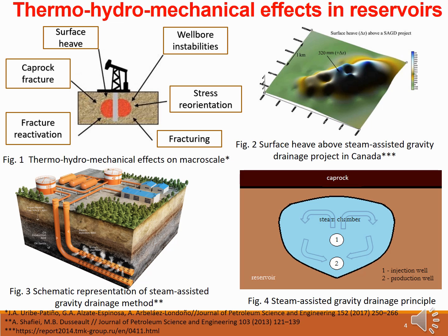This effect can be explained as the development of shear failure, which occurs in the reservoir due to the propagation of the thermal front. Moreover, shear failure together with microfracturing of the soil can significantly increase porosity and permeability and thereby magnify recovery factors. In this work, we propose a damage model which describes these effects in the steam-assisted gravity drainage method